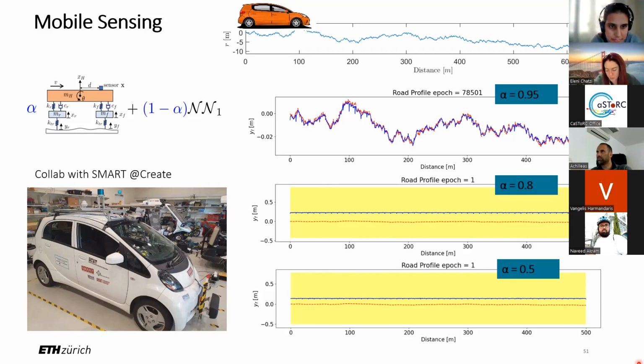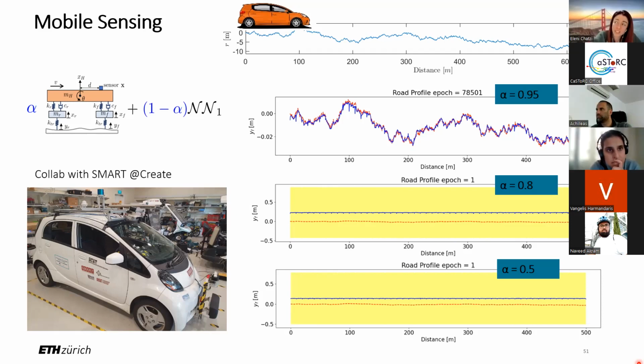It's a very good question. Practically, this is also something we have to account for. In different works that I did not include here, we have also shown how to develop indicators of malfunctioning of sensors so that you can maybe take them out of the estimation part, because of course it will affect the prediction, as you say. And in the indicators that we developed, which I showed in the beginning, we had that yellow or orange alarm for the case where the system is experiencing a situation that seems new.